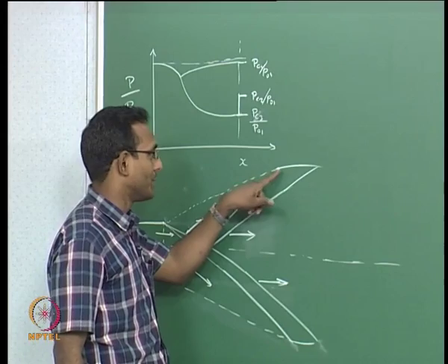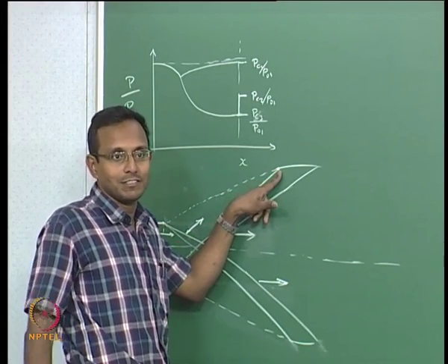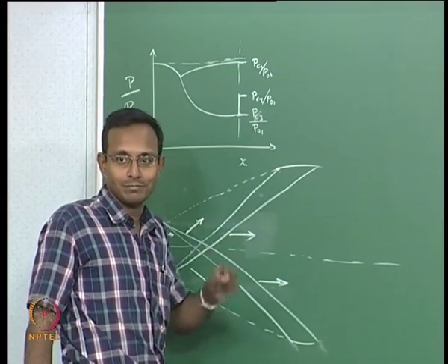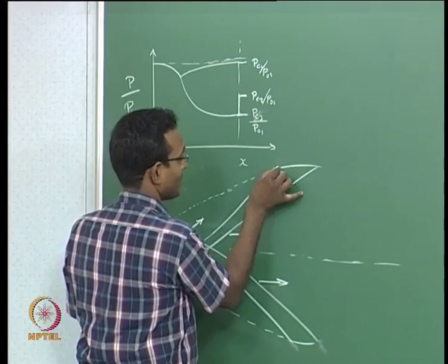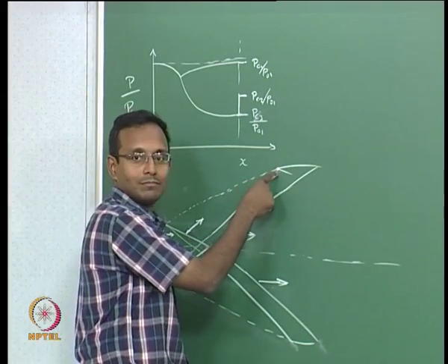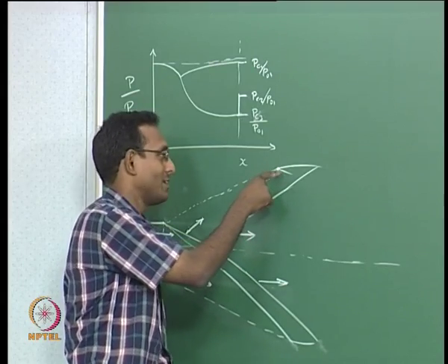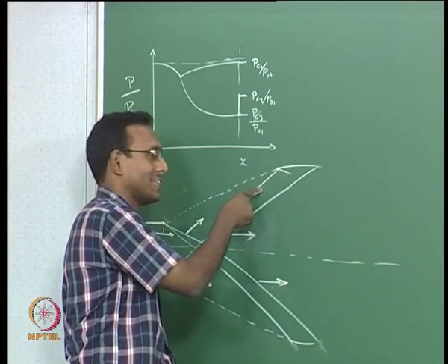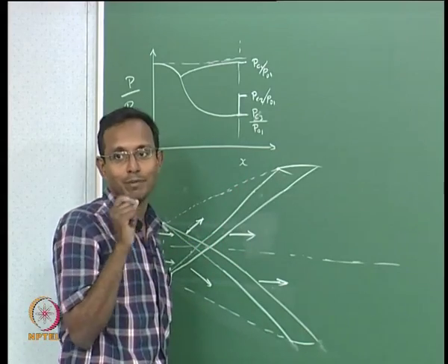That is why this becomes your boundary condition. It is telling you, I am not going to change, you have to change your pressure. How does it impose it? It forces a compression wave on top of this expansion wave to negate it at that point. It will be exactly equal and opposite value. It will be an expansion fan, a compression fan matching this exact expansion value, so that at that point it is 0 change in pressure.